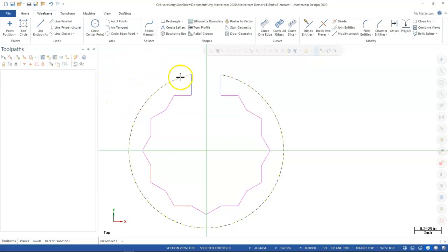I believe that I was selecting all of those with the window picks. So seeing those little highlighted backgrounds, still little wireframe things there, that would be a good indication that it's going to leave them if I click out of it. So hitting the delete button, right-clicking, hitting the delete button, make sure. And now I don't see any little triangles out on the outside.